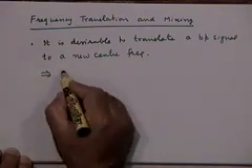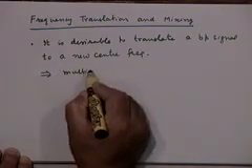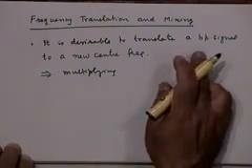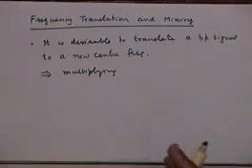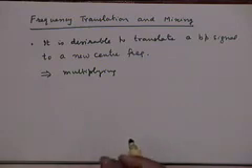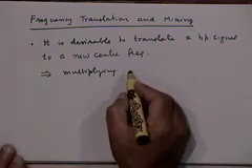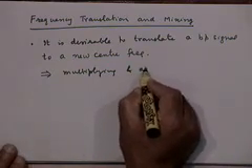Mechanism is multiplying the bandpass signal that you want to translate by a suitable carrier signal, which could be a sinusoid or cosinusoid, or a corresponding periodic signal, and appropriate filtering: multiplying and appropriate filtering.